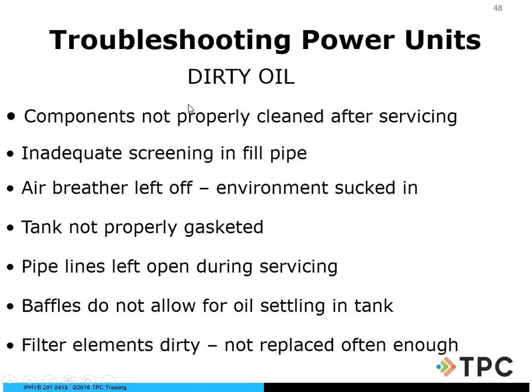Troubleshooting power units: dirty oil, components not properly cleaned after servicing. That is a big deal. It happens a lot. Air breather left off. Those are some of the things that we can prevent, as professional workmen, and everyone must do that. Pipelines left open during servicing.